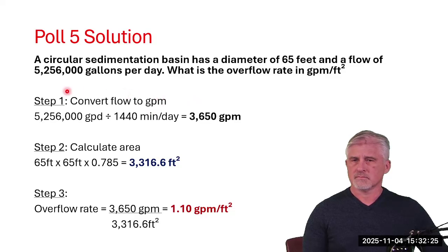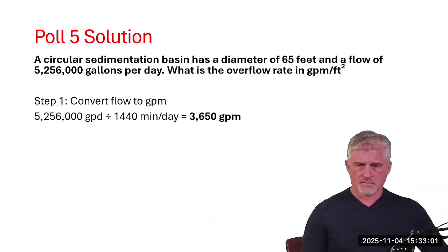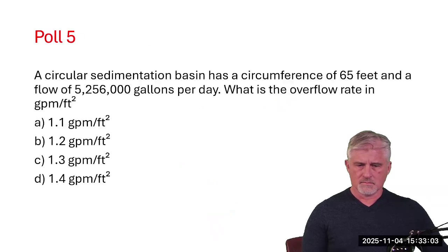And I'll go ahead and end this poll for now. I'm sorry if some of you are still struggling on it, just for time's sake today. Most of us said 3.2 gallons per minute per square foot. And the solution here, we multiplied 15 feet times 25 feet to get our filter surface area, 375 square feet. And we took our 1,200 gallons per minute divided by 375, and we got a filtration rate of 3.2 gallons per minute per square foot. Great job, everyone. And we're open for questions.